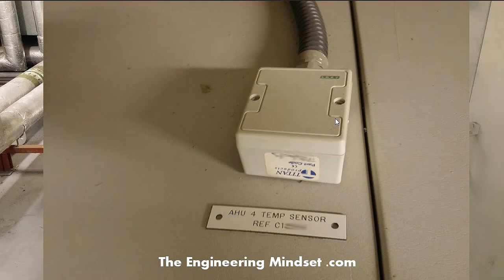I'll just show you an example of a temperature sensor here. So this is bolted to the side of the unit, maybe onto the top of it, and there would be various ones, and there's a rod coming inside the unit there taking measurements of the temperature of the air. And you may have noticed at the top here this tube sticking out, sticking through the top. That is your temperature sensor right there, and that's taking the measurement going onto this heating coil here, and will dictate through the controls how that should operate in response to that.